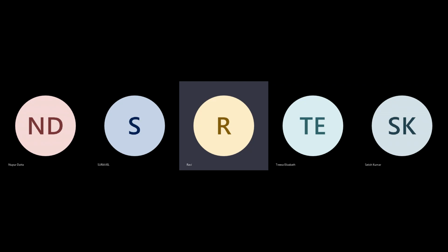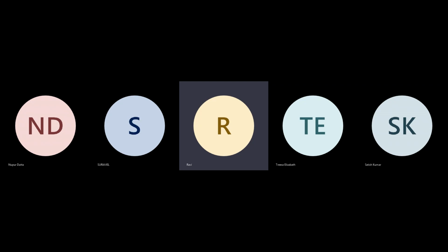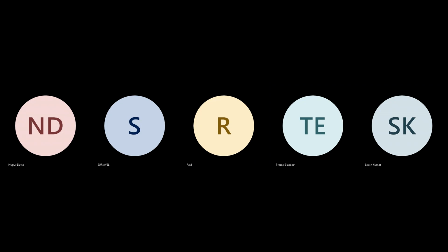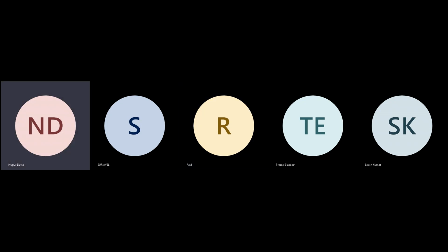You can put that attribute. You have to set different colors and you source that file. After you have done your placement, it will tell you how the color map is. Then you can look at this color split and you will be able to identify whether it is split or not. Simple. Or in the GUI, you have to select and right click, there will be a color. You set that color. You understood? Yes, sir.